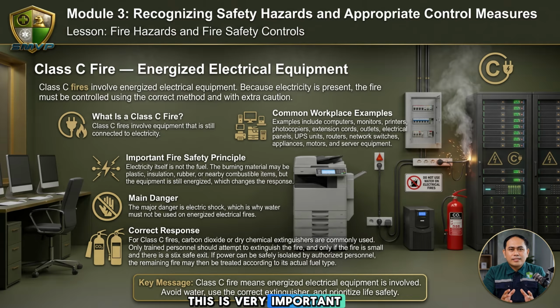This is very important. Electricity itself is not the fuel. The fuel may be plastic, insulation, rubber, or nearby combustible material. But because the equipment is energized, the electrical hazard changes the way we respond. For example, if a printer catches fire while still plugged in, or if smoke comes from an outlet or server cabinet, we treat it as an electrical fire hazard. The danger here is electric shock. That is why water must not be used on energized electrical fires.